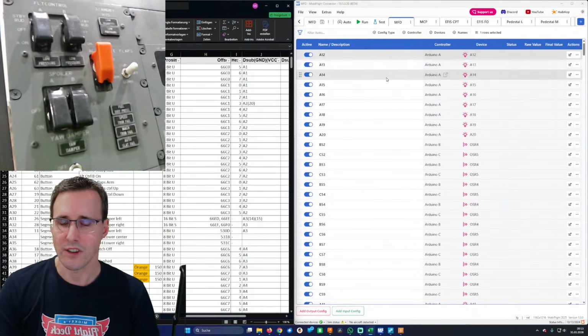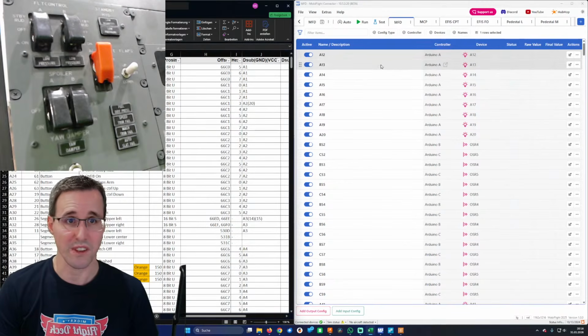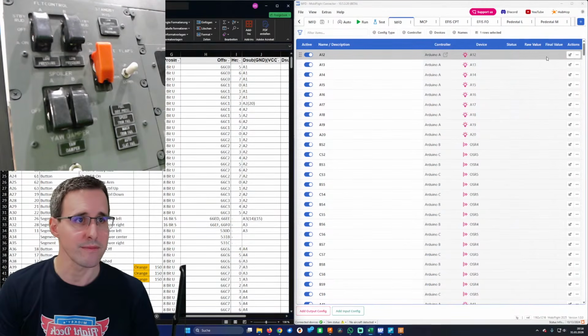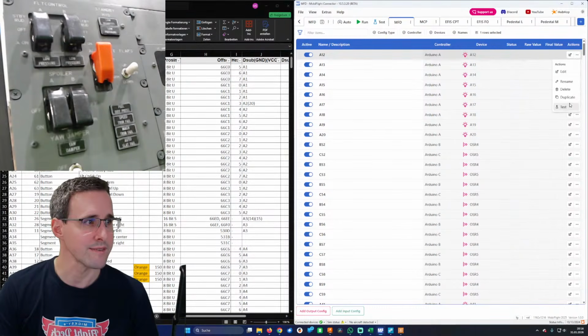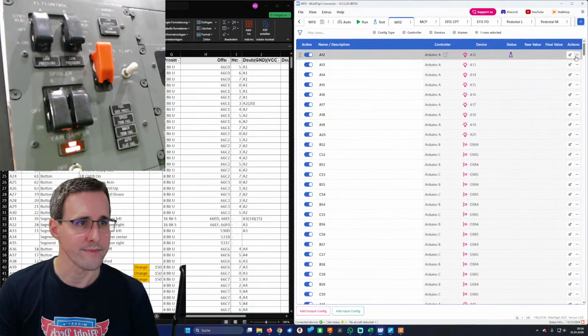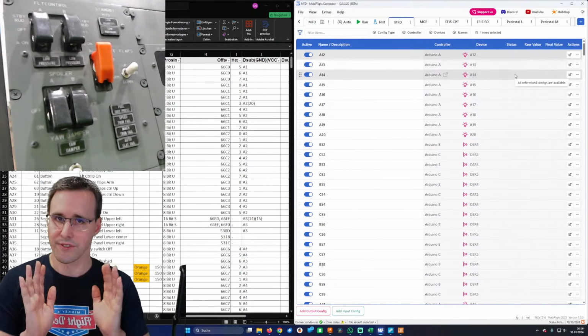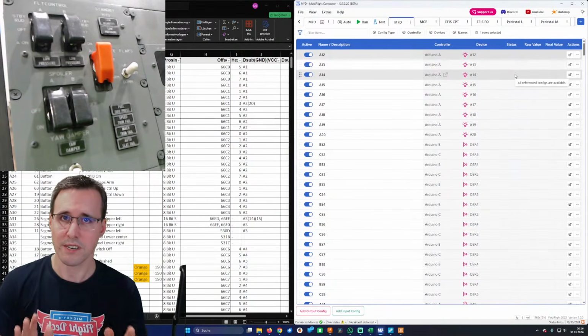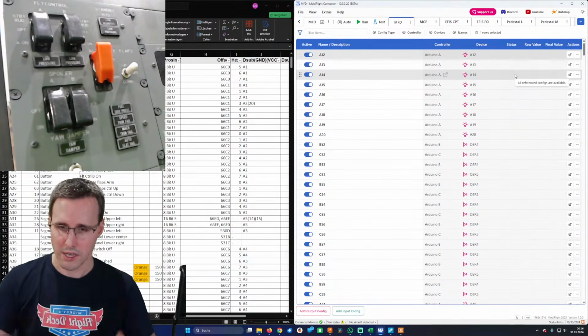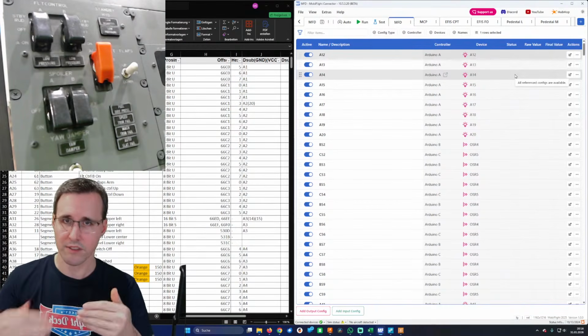Let's test roughly if the thing is working at all. And MobiFlight has a test function here. So we just have to click test. And there it is going on and off again. So the simple hardware connection, Arduino to the LED, this is working.